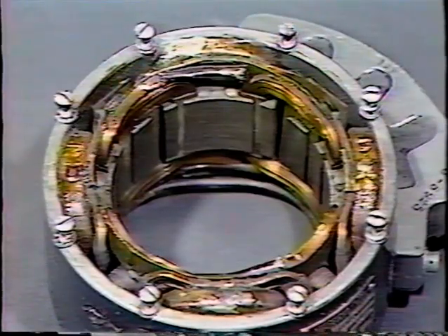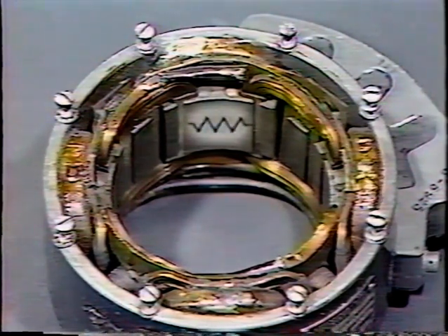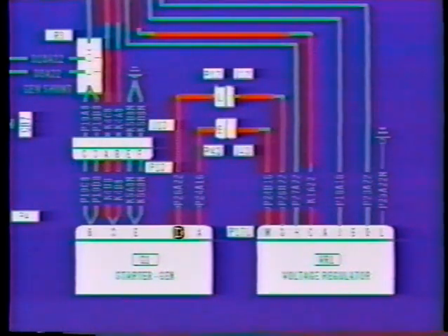One, it increases the resistance in the shunt field windings within the generator. This action stops or severely reduces the output of electrons produced from armature rotation within the field of the generator. This signal is sent to the starter generator's pin D from the voltage regulator's pin G. Two, the starter generator's pin A also receives a signal from the voltage regulator's pin M. One volt is applied during the start process to allow the starter to return to a generator at the completion of the start process.